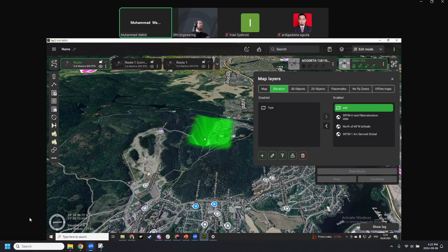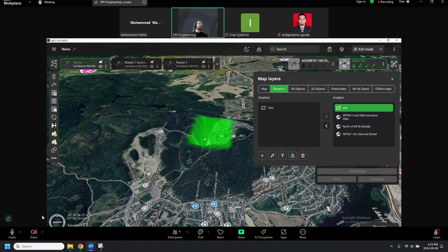Unfortunately, I don't think so. I might be wrong, but the magnetometer, among many other sensors, are just not compatible with the drone autopilot, so we can't control them via UGCS. So they are controlled via the CPM and the SkyHub. Or if it has its own logger, then it does it on its own.